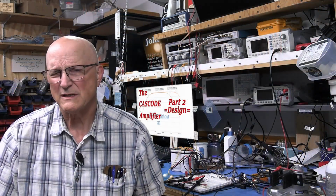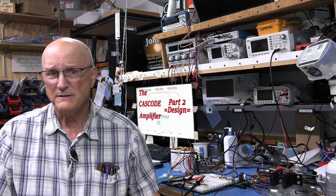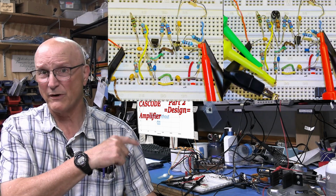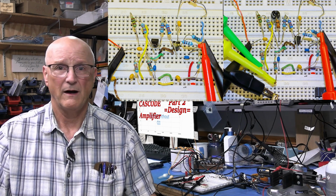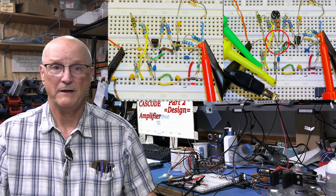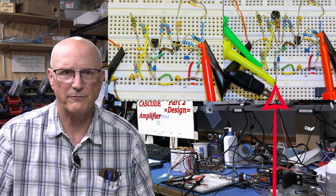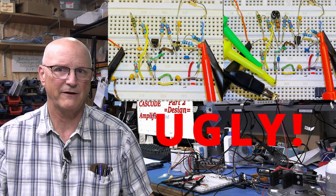Well, my first step was to select standard resistor values for each of the resistors in the design. Then see if I could somehow find these in my collection of resistors. Well, here are the pictures of my very ugly breadboard setups. The one on the left is the whole CASCODE amplifier. On the right, you can see the modified CASCODE amplifier missing its Q1 and the addition of a resistor to draw Q1's base current, as well as the separate power supply connection for the collector power. You can see that I had to use multiple resistors to achieve the right values.